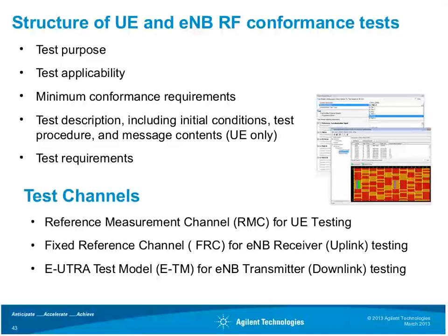Here's the structure of the conformance test. They define the test purpose, test applicability, the minimum conformance requirements, the description, and the test requirements themselves. Because there are so many degrees of freedom within the LTE, you have to carefully define the conditions under which you do the testing so you can compare the results. So for each of the test cases, they set up the test requirements and test channels.